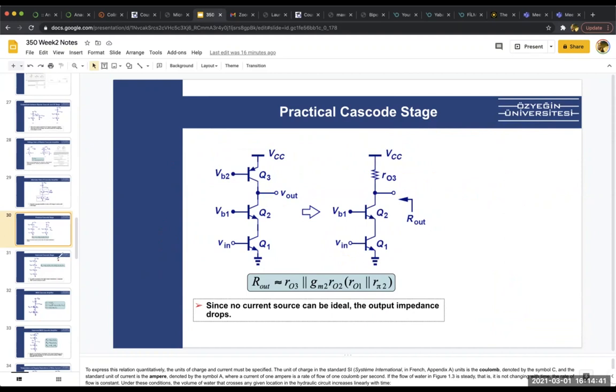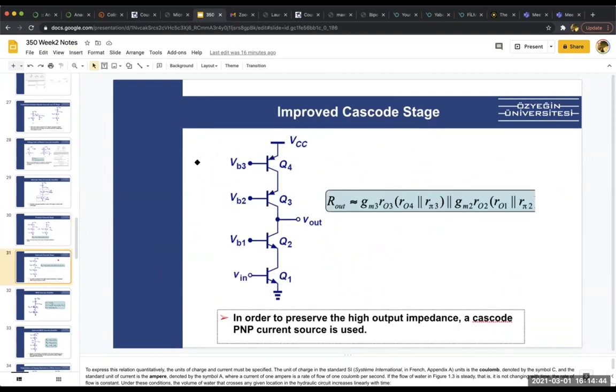The circuit can be even more complicated, and we can cascade them. The reason we are adding another cascode is that we are increasing this resistance. If there is only one transistor, the resistance Rout would be smaller. Now we added another one. This one increases, this one increases. Can we add another one? Well, we can, but now, as I mentioned, the issue is headroom, because all these transistors take from your headroom.